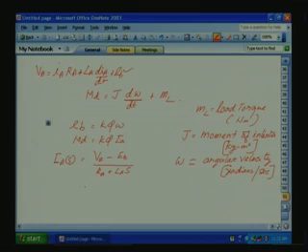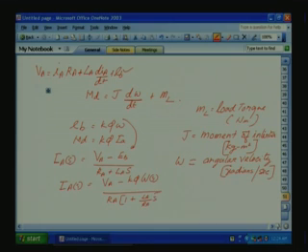So from this one, again we can modify this equation, that is IA(s) is equal to VA minus, now we will bring the EB here, EB is equal to K phi omega(s), divided by RA into 1 plus LA by RA into S. So this is in the time constant form, 1 plus ST, that form.